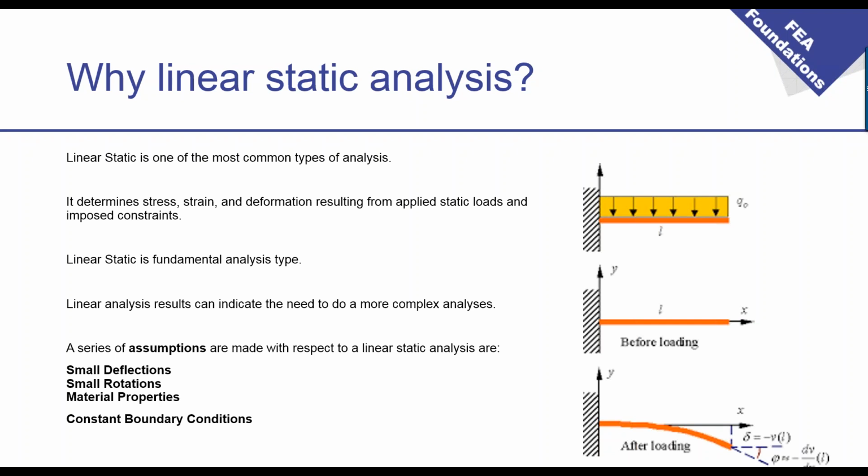And of course there are several assumptions with respect to linear static. If I want to analyze my model using this type of analysis, it should keep small deflections. What does it mean actually? You have to compare the deformation with the global size of your model. The deflection should be a couple of percent of your global size. A similar situation refers to small rotations.